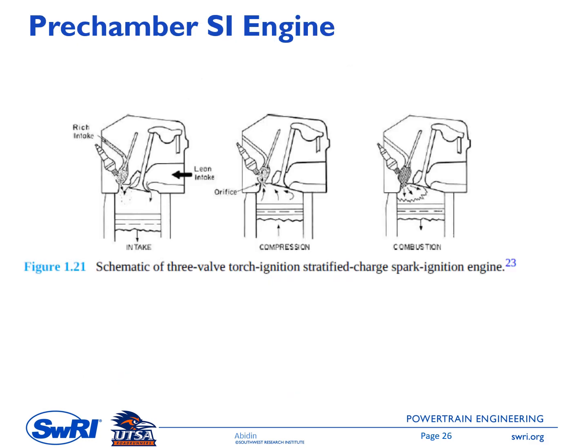Next one is the introduction of the pre-chamber spark ignition engine. In this case, we have a main chamber and a pre-chamber. In this pre-chamber, we have a spark plug. Depending on whether this is an active or passive pre-chamber, we might have additional fuel injected or introduced directly to this pre-chamber. If it is an active pre-chamber, we will have additional fuel directly to this pre-chamber. If it is a passive pre-chamber, then we only have the fuel introduction through the main injector or through the intake port.